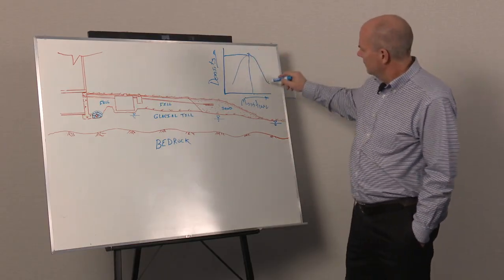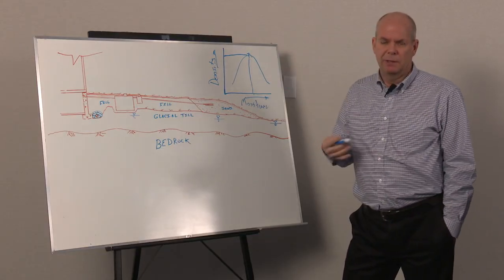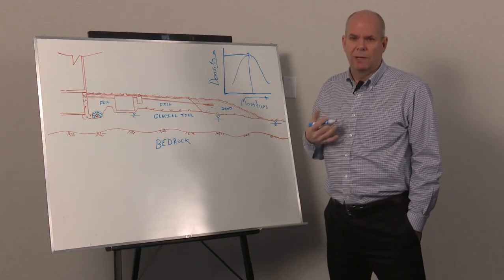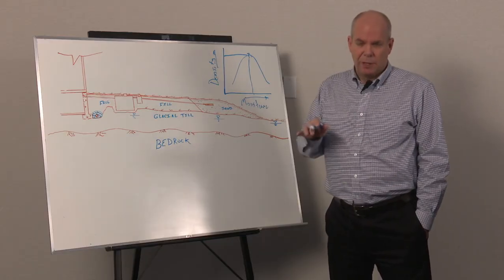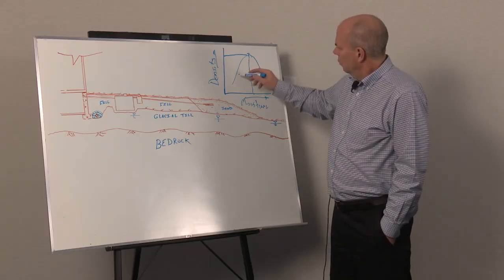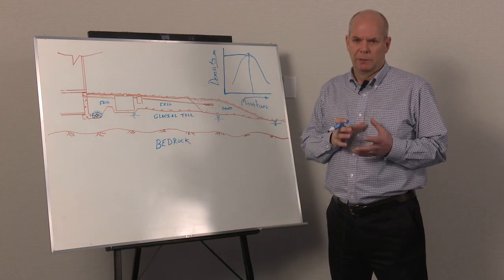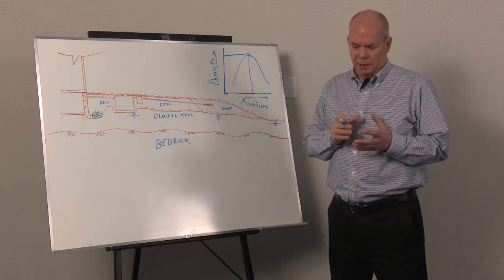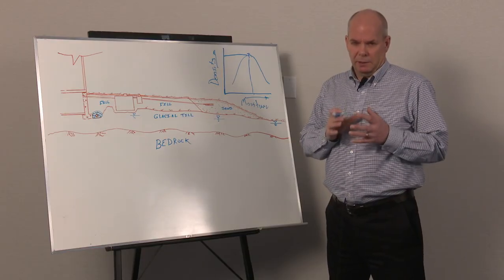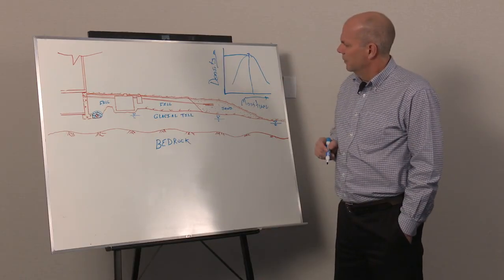When the material gets very high in moisture content, it loses strength, and you'll notice when you're dealing with clay and driving over it when it's wet, it'll be extremely spongy, the trucks will rut it, you get a lot of movement. When the material is very dry, it goes in typically with lumps, and it can look very good when it's being trafficked. It's very solid. These lumps, though, can give you probably more problems than the wet material.